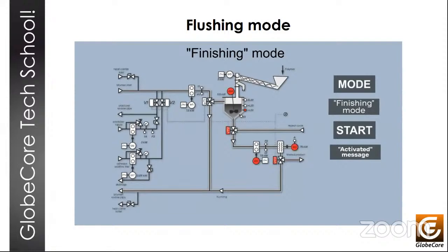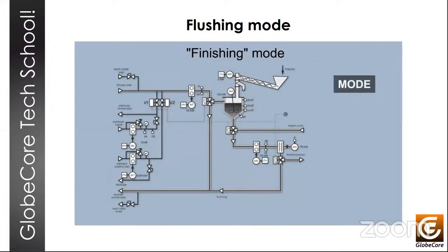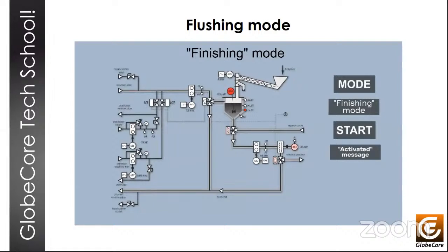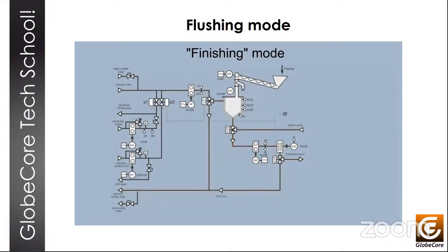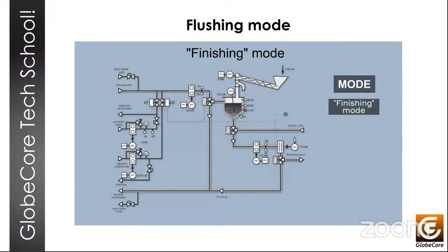And after the mill spools up, the M2 pump for PMB starts as well. All of these components run for about 60 seconds, maintaining the bitumen level in the mixer. And then the bitumen supply pump M1 stops. The VT1 valve switches to supply bitumen to the return line, and the bitumen is worked from the mixer. And when the low-level sensor 1 is off, the VT3 valve switches to supply bitumen to the outlet.